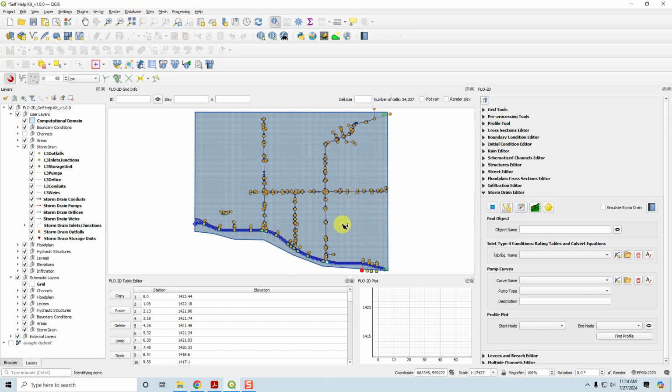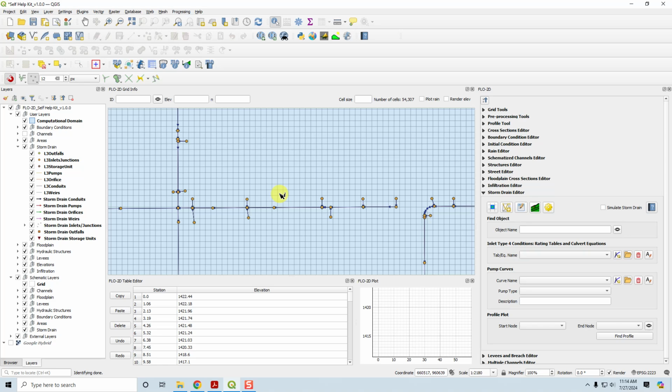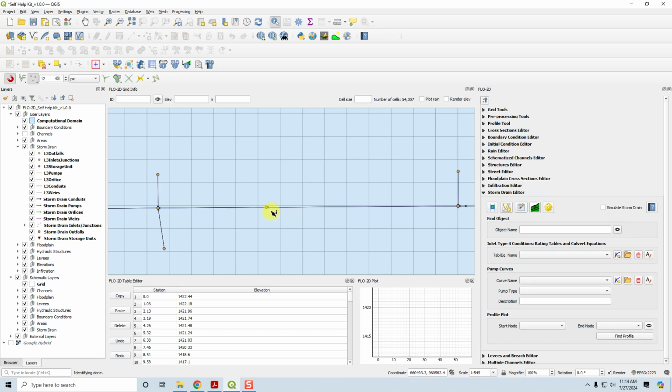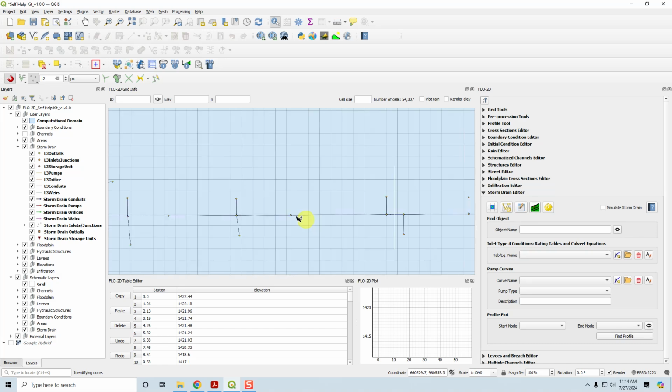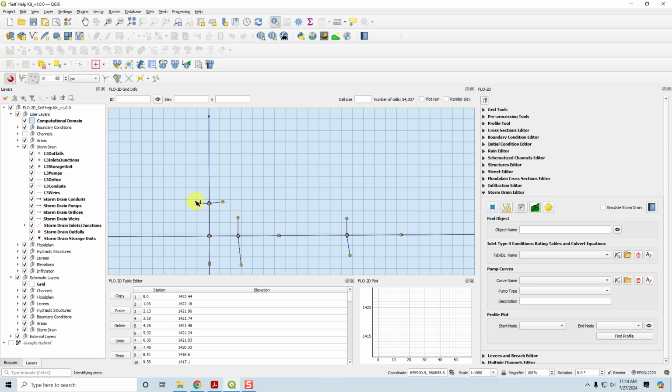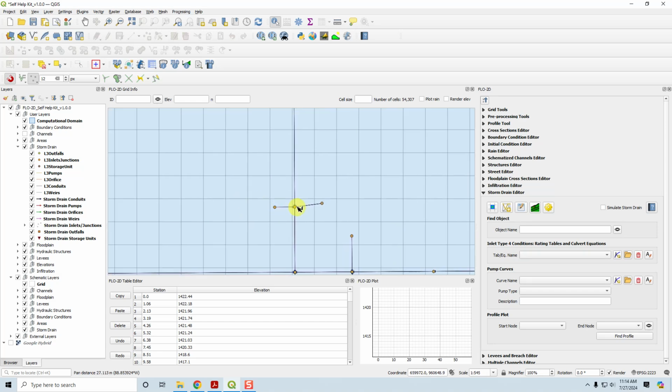If the numbers match, everything went well. If the numbers didn't match, it will give you a list of data that you need to go to, so you can go find the data that was broken. So what this tool does is it looks for a conduit. So let's get on our conduits, and we're kind of done with these, so let me uncheck these real quick because we're kind of done with those.